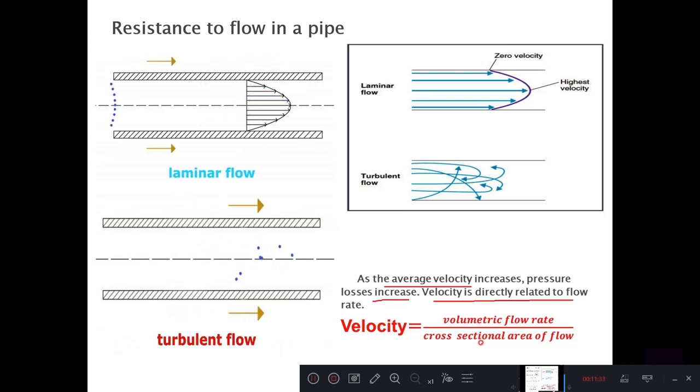Smaller pipes cause a greater proportion of the liquid to be in contact with the pipe, which creates friction. Pipe size also affects the velocity. Given a constant flow rate, decreasing pipe size increases the velocity, which increases the friction also. The friction losses are cumulative as the fluid travels through the length of the pipe. The greater the distance, the greater the friction losses will be.